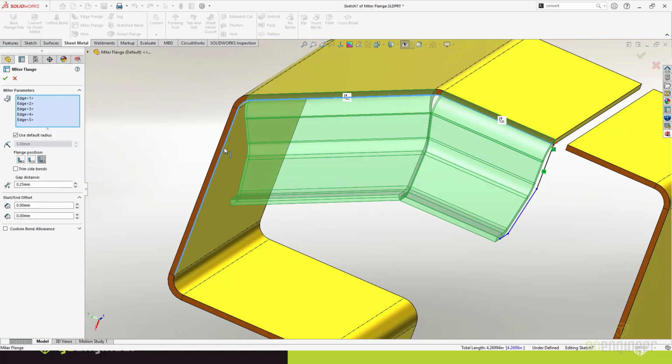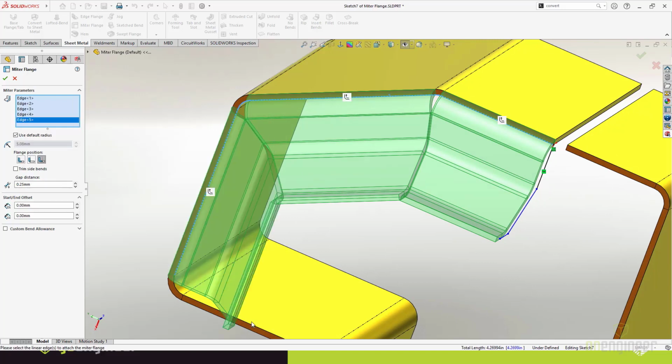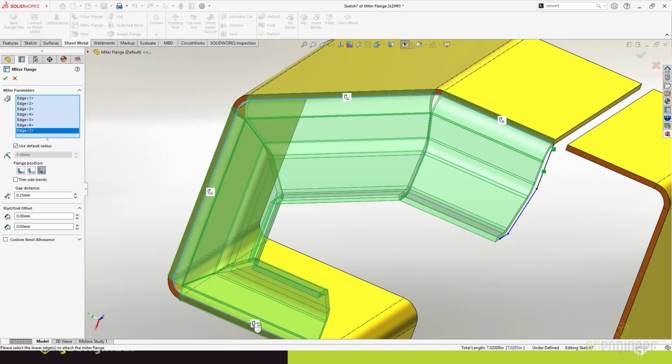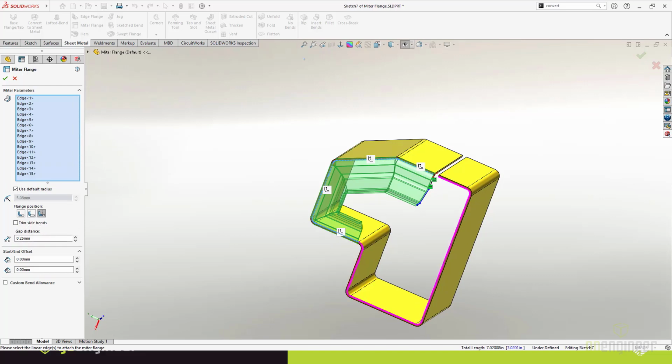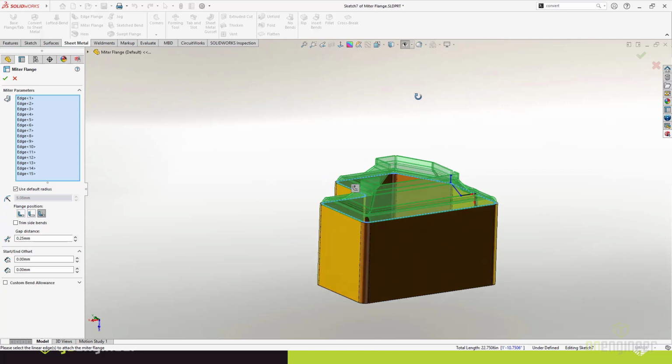This one will get really bad. So look at how it trims that back. Look at how it trims each of these back. And what's also happening here is this little propagate to tangent button pops up anytime you pick these edges. So if you didn't want to pick them individually, you can just pick one of those and it will pick the rest of them. But you can see how compound this gets. We'll wait for my preview to pop out. One little sketch creates what's essentially 3 different bends on this, but it automatically trims those in the corner.